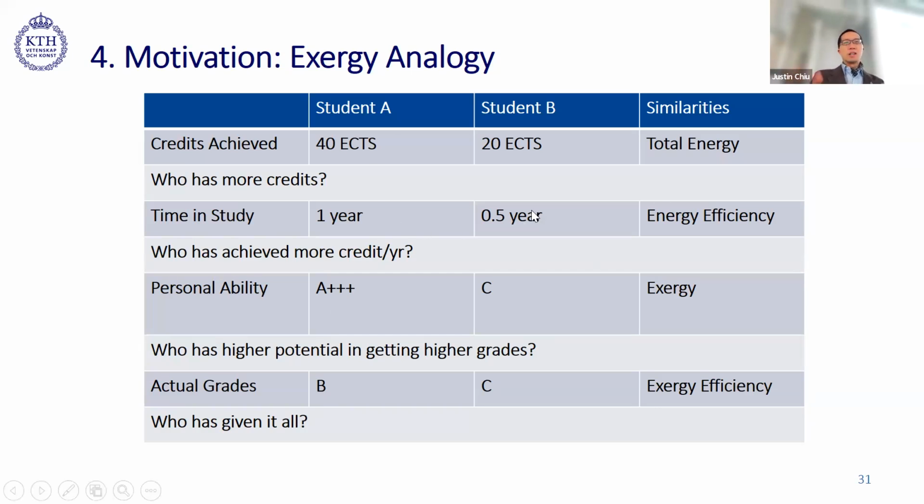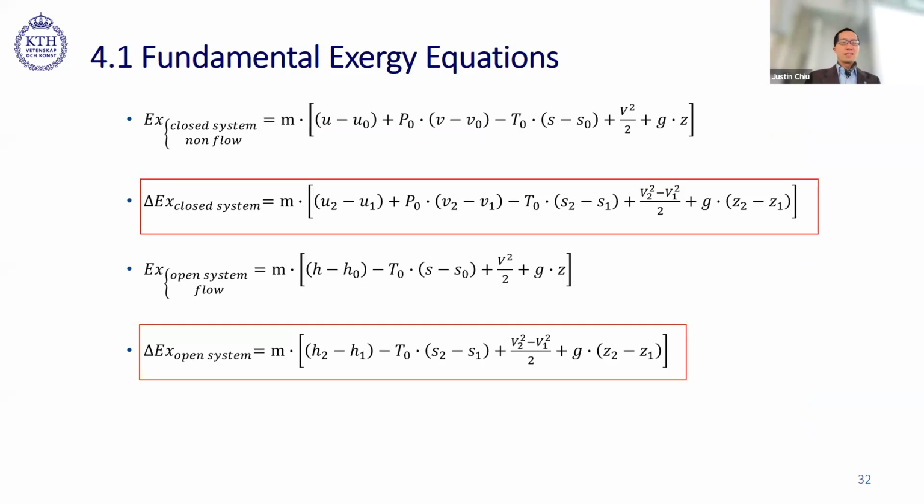So one is the total amount of energy, I'd say, and the other one is more the capability of providing work. In terms of thermal engineering, it is actually the temperature level. The higher the temperature level you can get out, the higher the Exergy efficiency. And you know that electricity has the highest Exergy efficiency because electricity can be converted to any source of work, mechanical, thermal, etc.